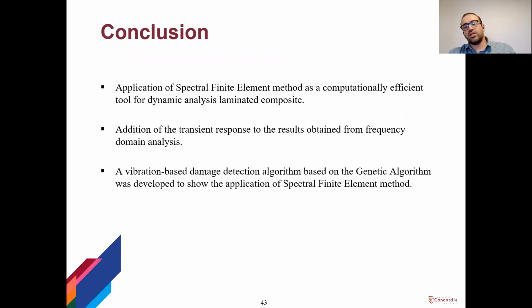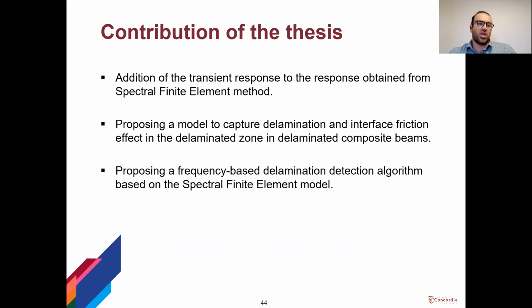So overall, the application of the spectral finite element method as a computationally efficient tool for dynamic analysis of laminated composites was studied. The transient response was added to the results obtained from frequency domain analysis, and the vibration-based damage detection algorithm based on genetic algorithm was developed to show the application of the spectral finite element method.